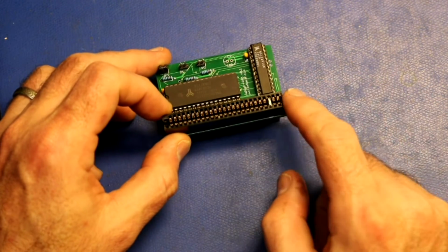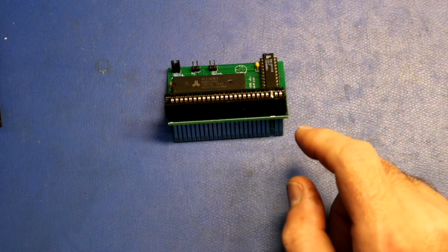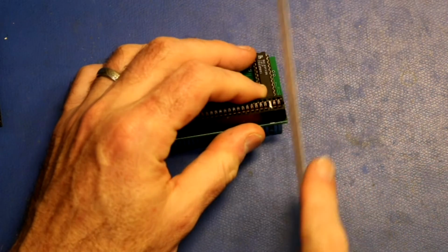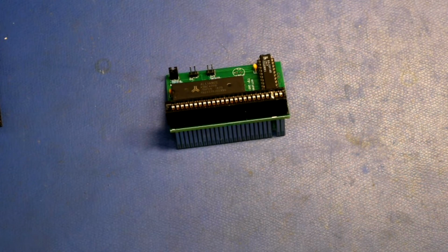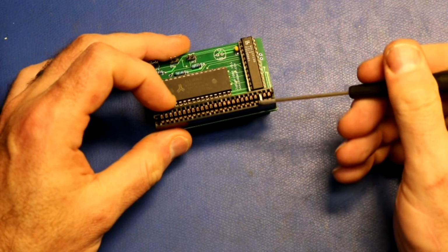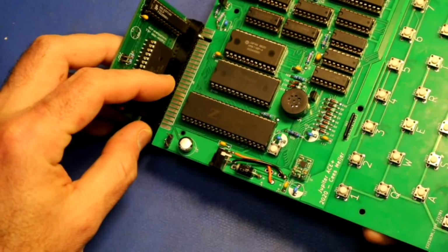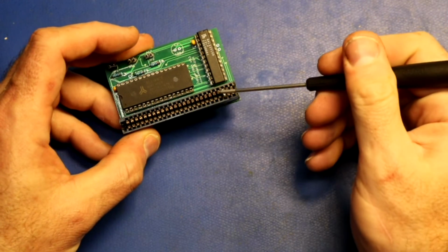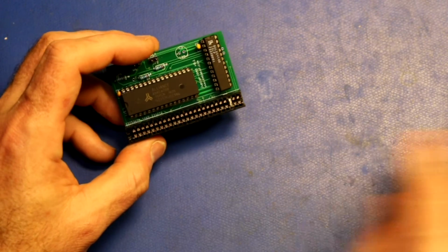Most of your edge card connectors will be closed on the ends. So what I did is I took a normal edge card connector and my hacksaw blade and just hacksawed on through it, and the other side hacksawed on through it, and then you end up with one that is open on the ends. And then you want a key, because this is keyed, to match it so that you don't get it off by one. I took a couple pieces of bare wire, stuck them in there, and just put some solder on it. So that makes a good key, lines everything up right.